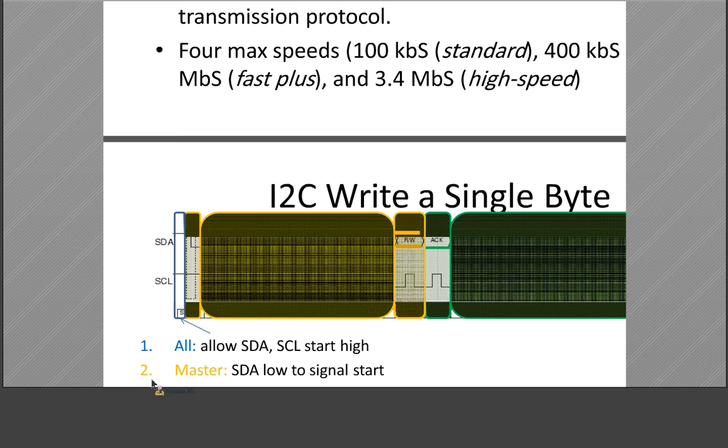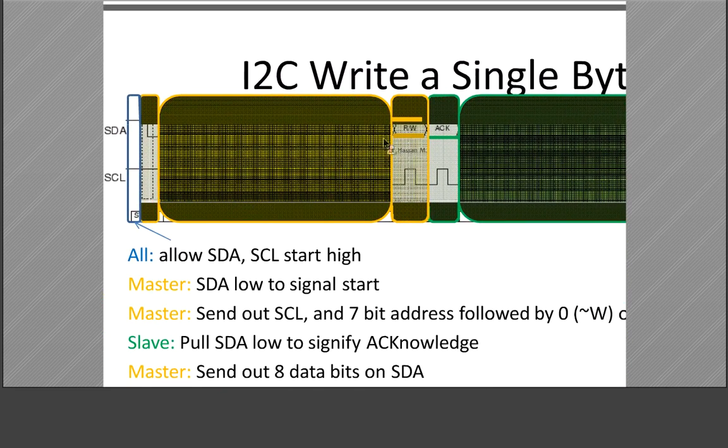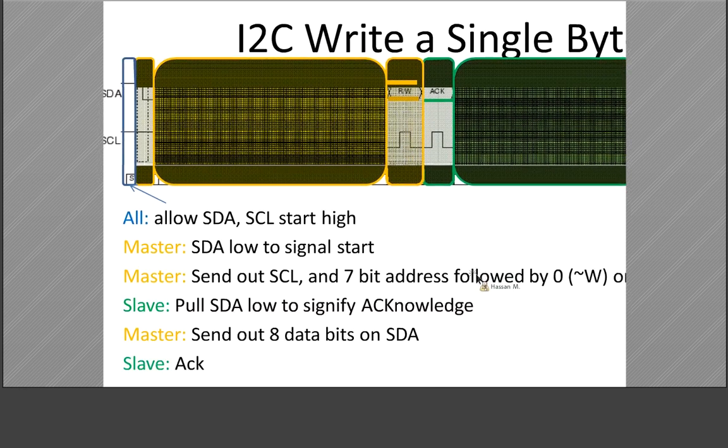Here you see SDA and SCL, and here we see data bits. Here is the read/write bar bit, 1 for read or 0 for write.